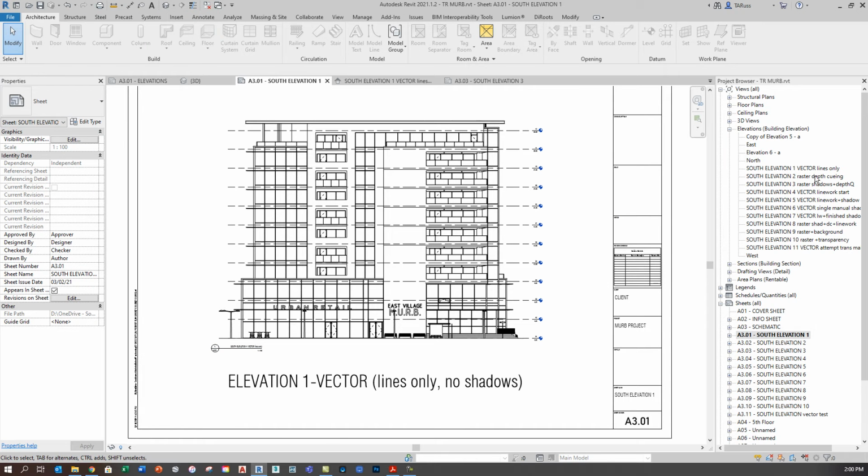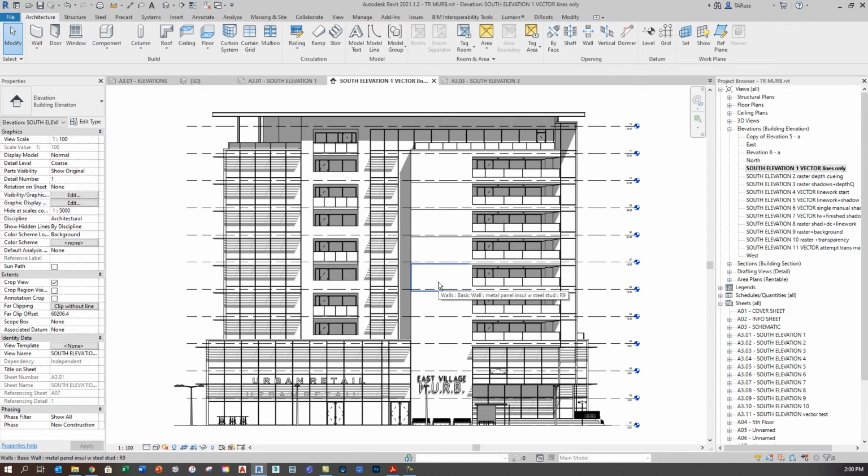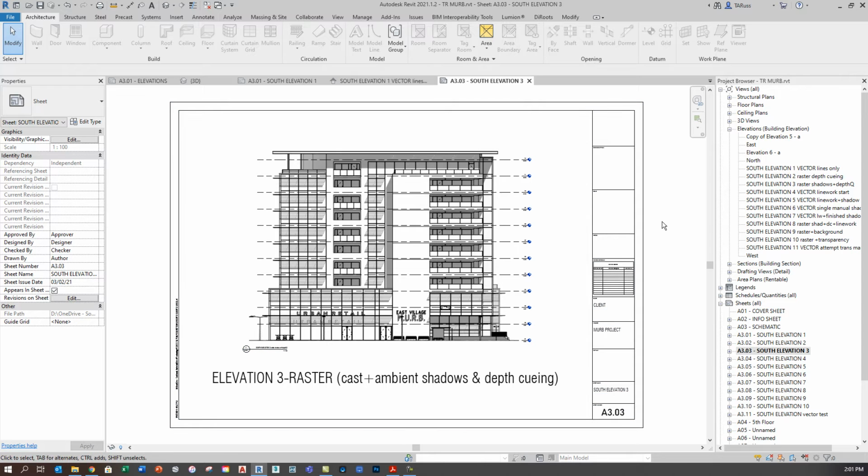And if we go to the sheet view, all we have to do, of course, is turn on the shadows back in the actual view itself. So in this case, I would just turn on the shadows using this little button down here on the lower left, and no problem. We're going to have a nice display of shadows here, which gives the viewer an indication of what might be in the foreground and what might be in the background. So we take this view and these properties and we set it up on a sheet. And once again, we're pretty confident it's going to generate a nice looking elevation.